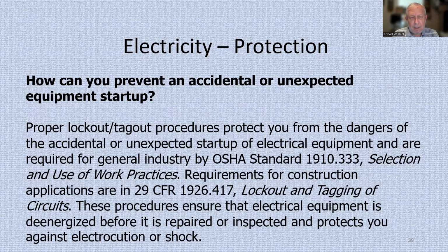Well, that's double insulated. If you go to Home Depot or Lowe's and look where they have all their power tools, you'll see some that have only a 2-prong plug. And you look at the nameplate on it, and it'll have that square within a square to show it's double